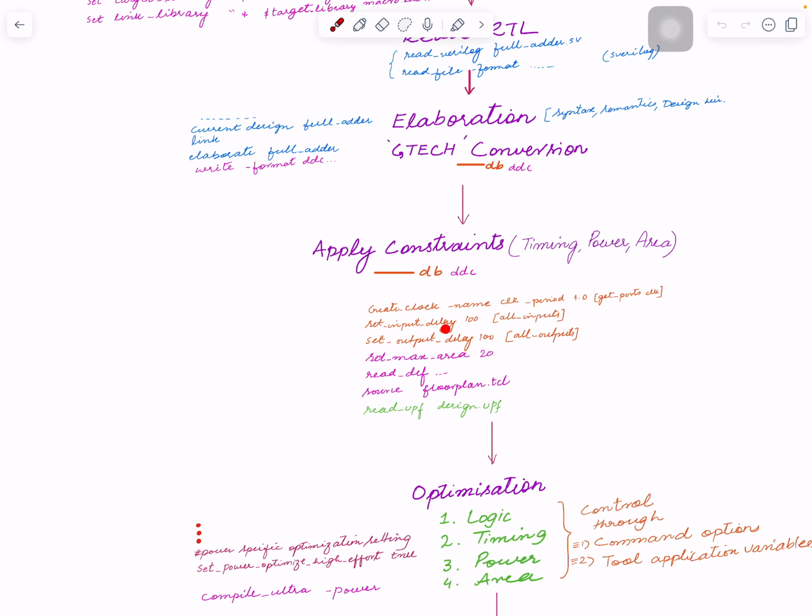Here's another one, input delays. Input delay is the external delay. The signals coming into your chip or your design are getting some delay outside, and they are eventually consumed inside. So in the timing constraints, you want to understand how much delay they have outside. Again, I will cover what input delay means and what output delay is, but just here, you can apply some data. There are so many other types of constraints you can apply, with different keywords and syntax. But the thing is, you need to create a Tcl file which provides timing constraints like this.